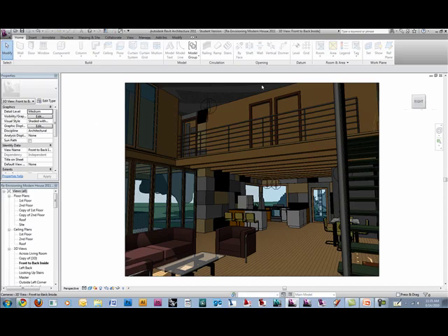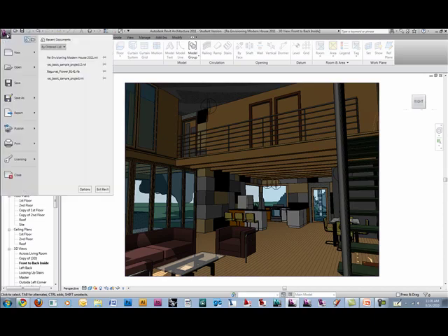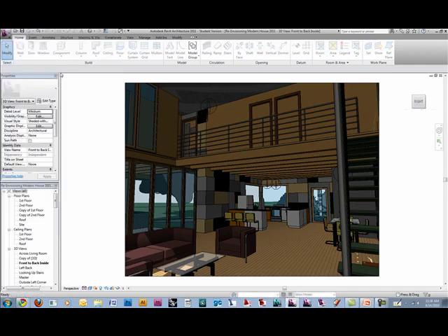So today we're going to edit an existing family. We're going to show you what a family is from scratch, a little one, and then we're going to do something bigger, like if I want to replace this chair. You're looking at a project, and I'm probably going to end up loading this stuff back in as we go along. But to start a family, we click the Revit button, the R button. We're going to go New, and we're going to say Family.